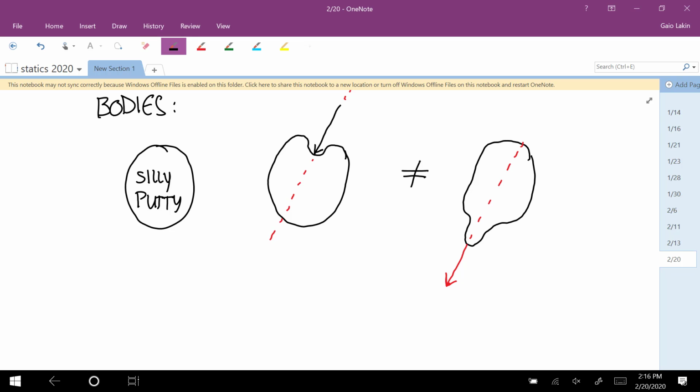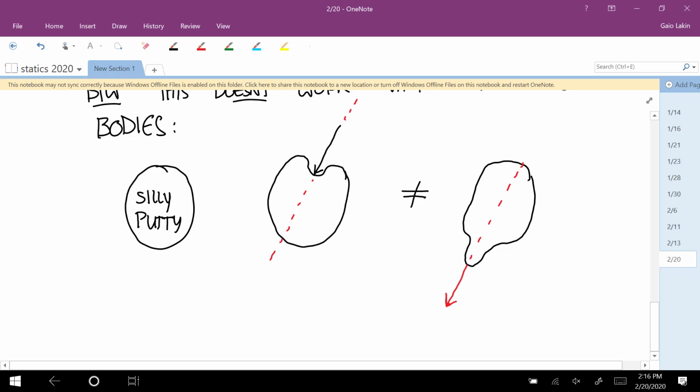Well, actually, that's exactly why it does work for rigid bodies, because the moments are the same. If you think of a moment, so we do it with cross products, but if you think of a moment as a force times its perpendicular moment arm, the idea of this is that you keep all the moment arms the same. So that's why it does work.